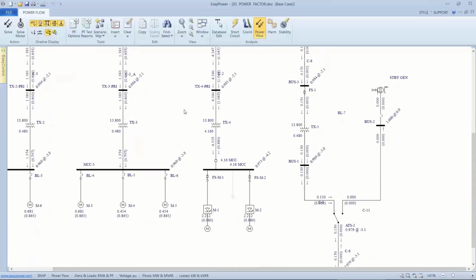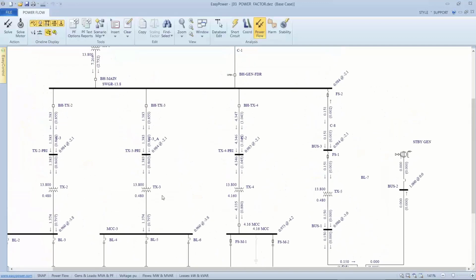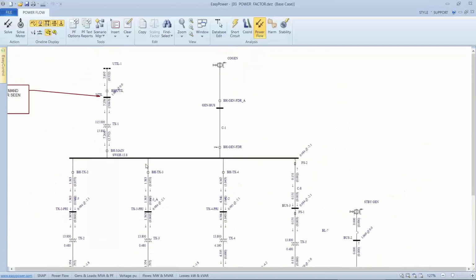And so the question is, what's the cost of doing a VFD conversion versus doing power factor correction? Again, there are other ramifications. The first of which is, depending upon what frequencies this VFD control will put on the system, I probably need to have some sort of filtering, which is going to impact the cost. And that's something else we need to do. So anyway, we've identified two different ways to eliminate the power factor correction issue with the point of coupling with the utility.